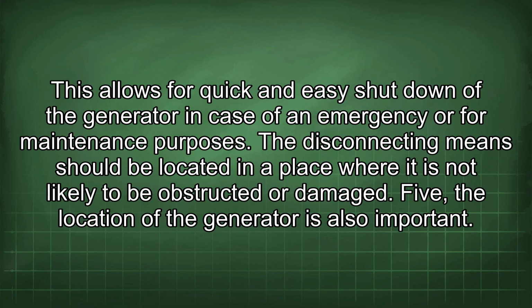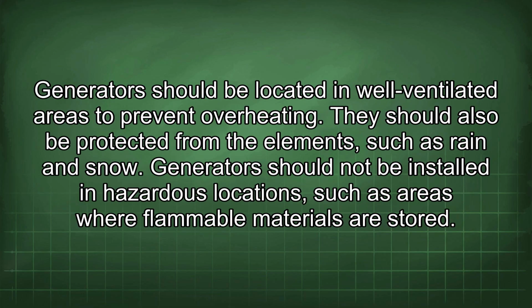5. The location of the generator is also important. Generators should be located in well-ventilated areas to prevent overheating. They should also be protected from the elements such as rain and snow. Generators should not be installed in hazardous locations such as areas where flammable materials are stored.